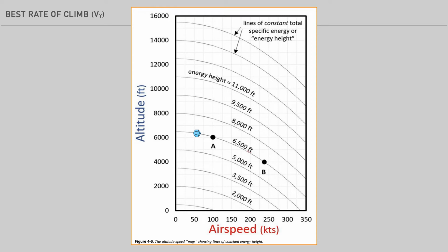To begin our discussion, we will keep flaps up, cowl flaps open, ailerons neutral, and use the rudder to maintain coordinated flight. The two variables to the pilot are the throttle or power, and the elevator to adjust the angle of attack.